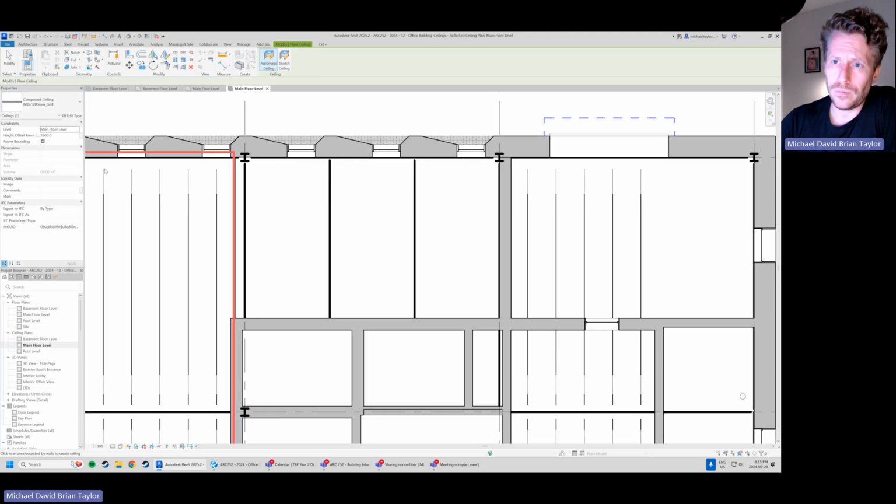And then see a couple of our constraints here. Really the only thing with the automatic ceiling, it's already picked our exterior kind of condition for how we're going to generate the ceiling, but you can pick your height offset. You can do it now, you can change it later. So you can see here the height offset, that is what we see in our reference drawing as the AFF, or above finished floor.